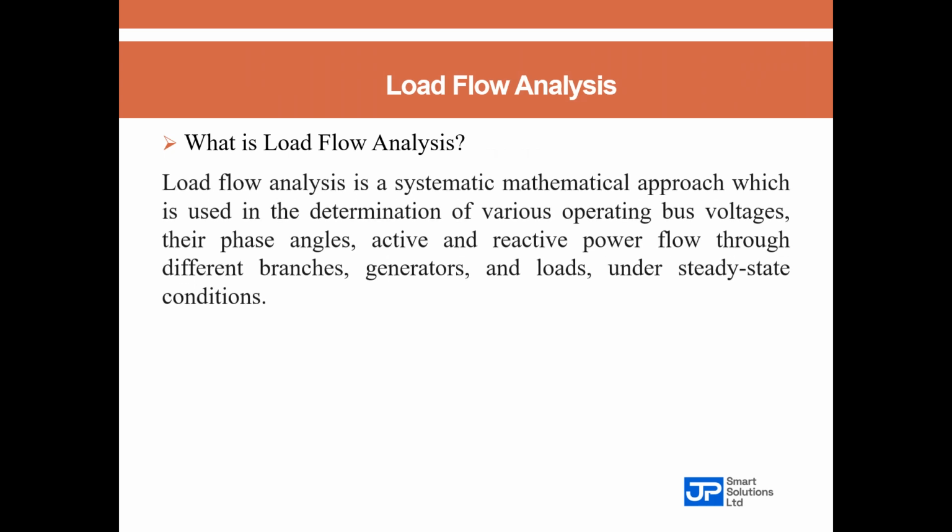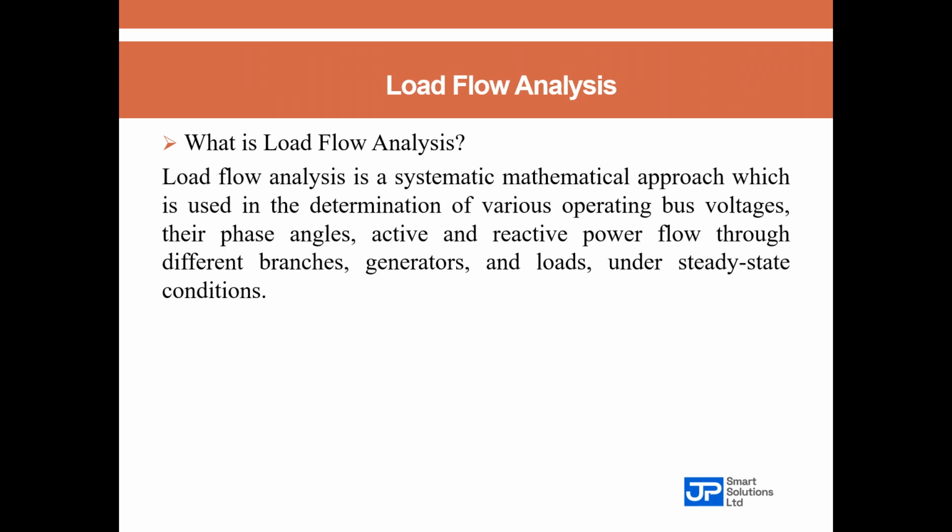So, a load flow analysis or a power flow analysis is a systematic mathematical approach which is used in the determination of various operating bus voltages, their phase angles, active and reactive power flow through different branches, generators, and loads under steady state conditions.